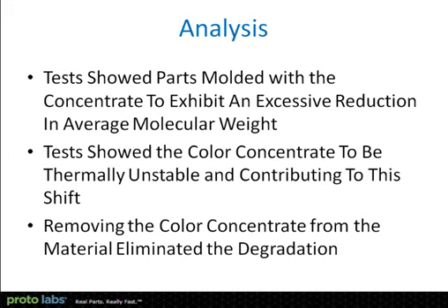And this is the kind of thing that we're running into more and more. It's important for people who are doing the formulations of color concentrates to understand that there is an upper limit on the melt flow rate of these concentrates. And when you start introducing materials with melt flow rates of 100, 150 into base resins with melt flow rates of 10 and 20, you are doing nothing but making life miserable for everybody down the line.